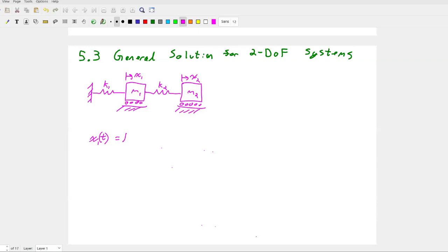And that is equal to A1, which will be my amplitude, times the sine of omega 1, which is my natural frequency for the first mass, or just my frequency for the first mass, multiplied by t, which is the time step that I'm at, plus phi 1. And all of that is in parentheses for the sine. And then this is multiplied by my modal element u, which we talked about, 1, 1. So for mass 1, mode 1,